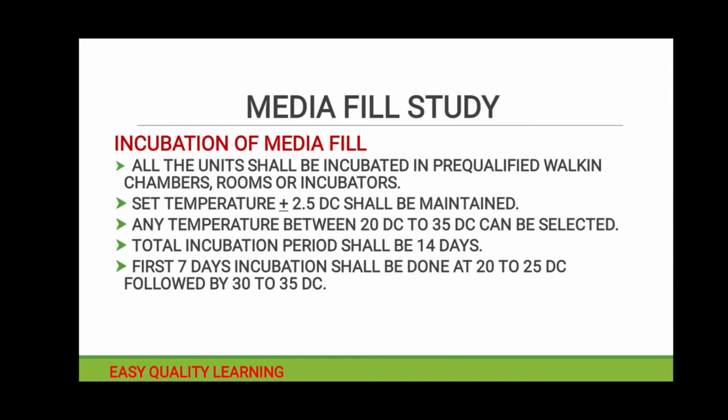Then incubation of media fill units. All the units shall be incubated in pre-qualified walk-in chambers. As we discussed earlier, it is a prerequisite that all your incubators or walk-in chambers shall be qualified. A set temperature of plus minus 2.5 degrees centigrade shall be maintained. Any temperature between 20 to 35 degrees centigrade can be selected for incubation depending on your justification.